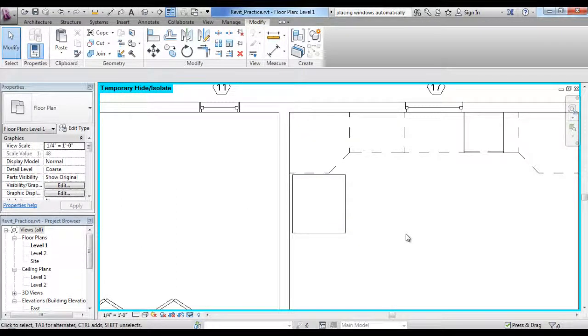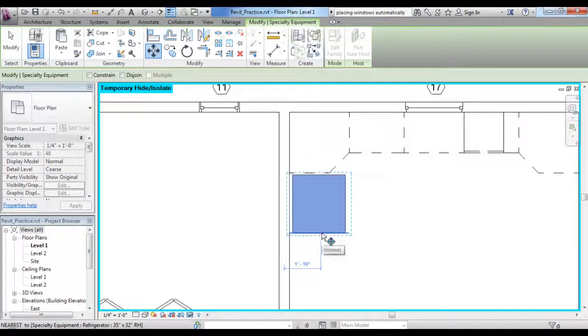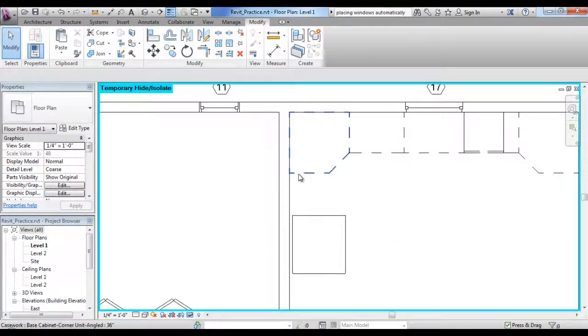So now you have this. That being said, we're kind of making this corner not real easy to get to. So let's pull it down about 2 feet more. So move, select. You can hit the enter key or space to finish the selection. Click and pull down, and let's type in 2. Enter. So now we have 2 feet here between here and the 1-inch opening.